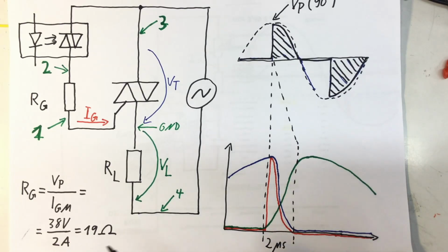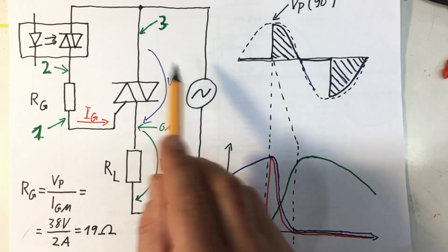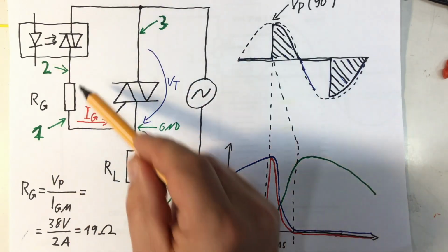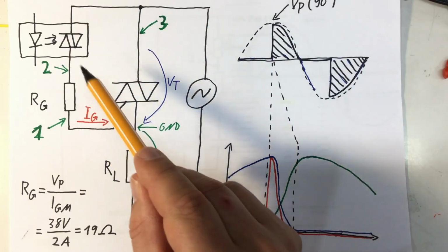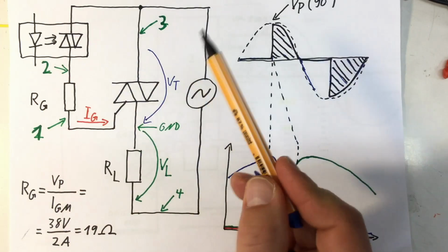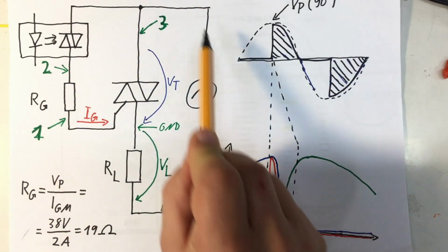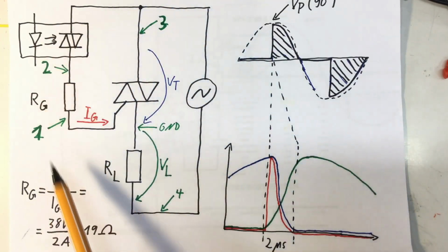No, I don't have a 19 ohm resistor, so I played it safe and took a 22 ohm resistor. Usual values you find here for mains AC applications are a few hundred ohms. But if you see on the internet some circuit like that and it says 220 ohms, or sometimes 110 ohms, you never know for what mains voltage such a circuit was designed.